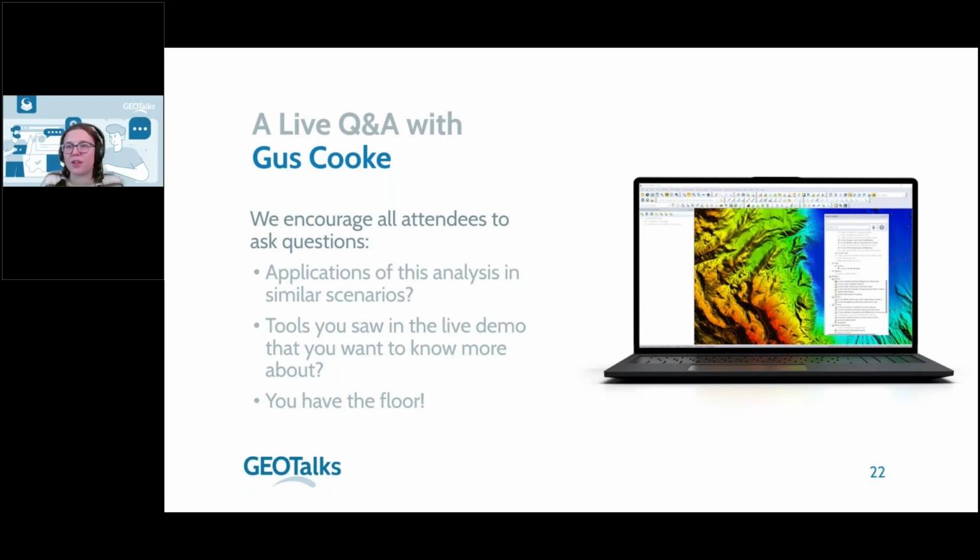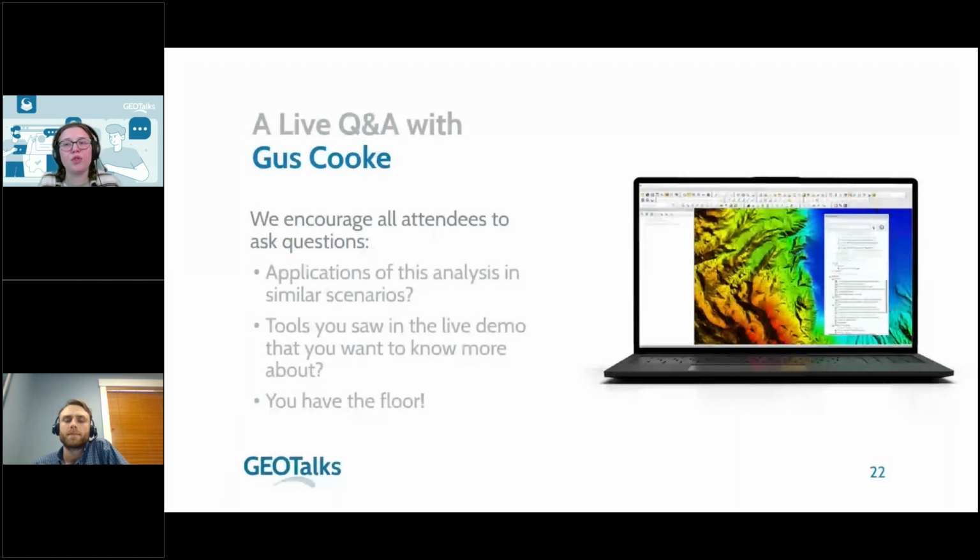We also have another question from someone wondering how to set up the shadow calculations and how to get there. Absolutely. So the solar shadow calculations tool is a Global Mapper Pro feature, it should be noted. So you need to have a Pro license, and it was added in version 26, so you want to make sure you're at least using that version in order to be able to access it. It's going to be in the terrain analysis drop-down menu, and it's also in the analysis toolbar.